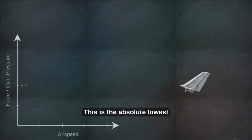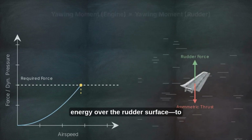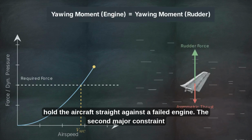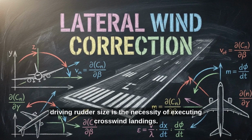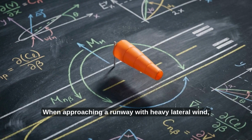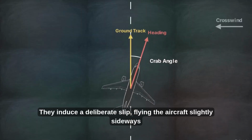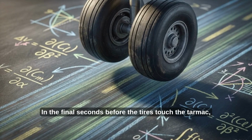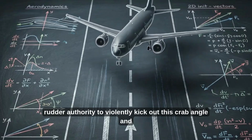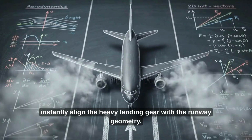This is the absolute lowest airspeed where the moving air still provides enough dynamic pressure, kinetic energy over the rudder surface, to hold the aircraft straight against a failed engine. The second major constraint driving rudder size is the necessity of executing crosswind landings. When approaching a runway with a heavy lateral wind, pilots utilize a technique called crabbing. They induce a deliberate side slip, flying the aircraft slightly sideways to track straight down the runway center line. In the final seconds before the tires touch the tarmac, the pilot requires immense rudder authority to violently kick out this crab angle and instantly align the heavy landing gear with the runway geometry.